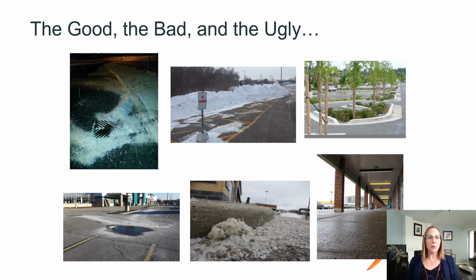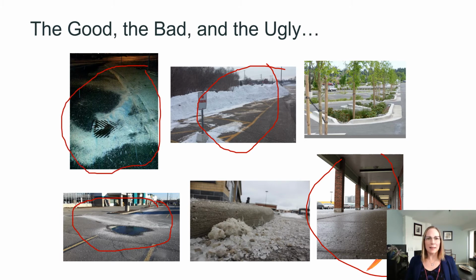We're looking to have more examples like these, and sorry, I'll get my pen again, where you have designated snow piles or covered walkways, and less of this, where you've got pooling areas that'll require more salt, way too much salt here. I'm guessing this is icy. These piles left over at the end of the winter, and then these landscaping features that look really nice, but they're going to get in the way of your snowplow equipment.